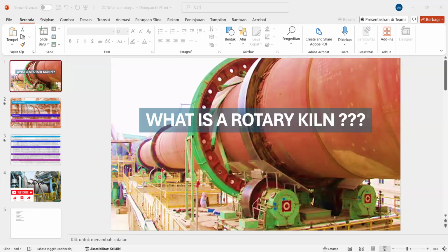The speed of material flow through the kiln is proportional to the rotation speed, so a variable speed drive is needed to control this. When driving through rollers, a hydraulic drive might be used. This has the advantage of developing extremely high torques. In many processes, it is essential to be able to hold the kiln stationary when the drive fails.